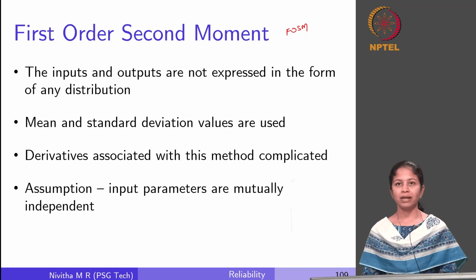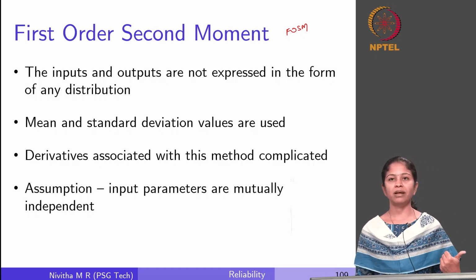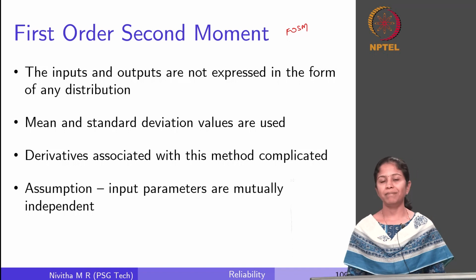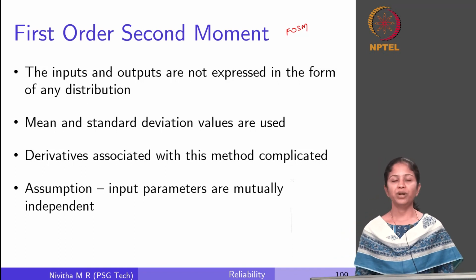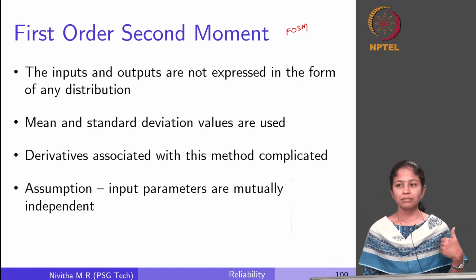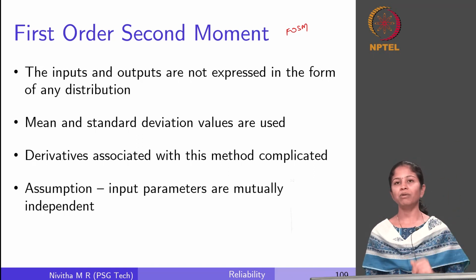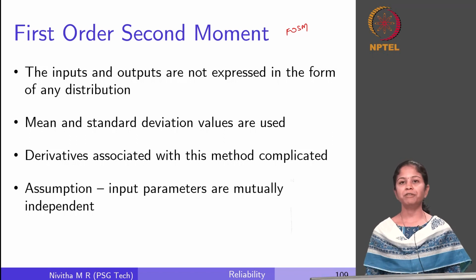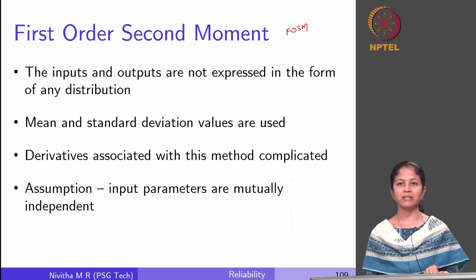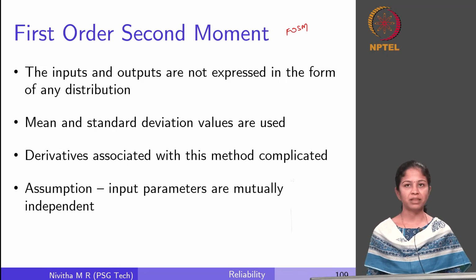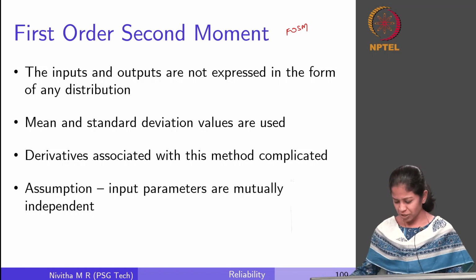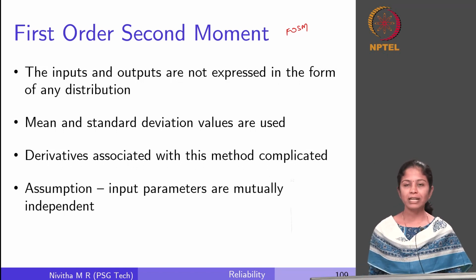Again, even in AASHTO 1993 we had seen that when we are designing one particular layer, when we are designing the layer coefficient for layer 2, you would have seen it depended on the resilient modulus of subgrade and thickness of the above lying layer, right. So there are a lot of dependencies, especially with respect to the stress state in a pavement system. So these dependencies are not considered in this particular method. So this is one method which is theoretically defined.